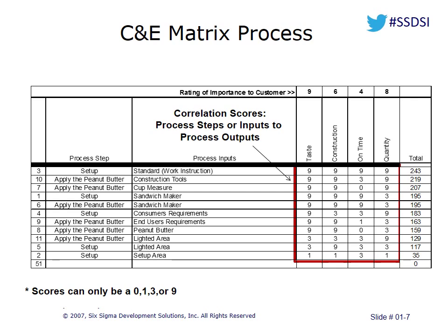Because once we move an input into that FMEA, one input can end up being 50 rows of data. It can get very big very quick. So the canned answer is to pick your first 5 top scores. You could pick your first 3 top scores, or 2 or 1, but usually 3 to 5 is kind of the canned answer.